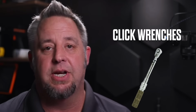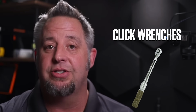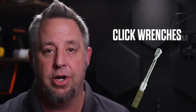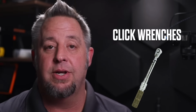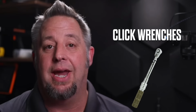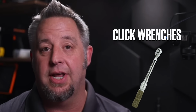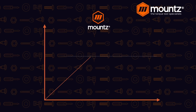And that's basically just because as the wrench is being pulled, once we hear the click, if that operator does not stop pulling it, or you may see operators that will double click, sometimes triple click, you are adding a tremendous amount of additional torque to the fastener, and that may not even be something that the operator is aware of. So if we look at this on a graph, you can see we've hit our torque value, the wrench clicks, but if we keep pulling on that, we are adding additional torque to the assembly.